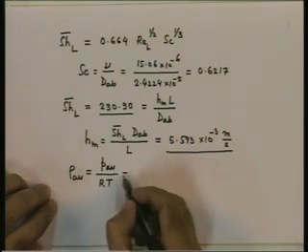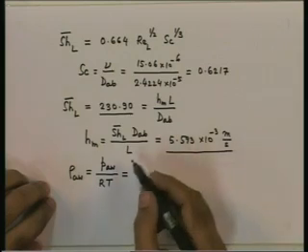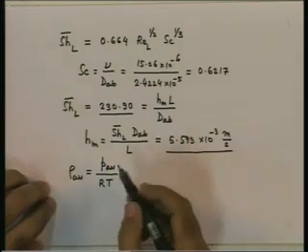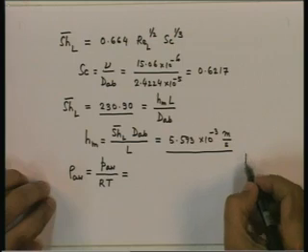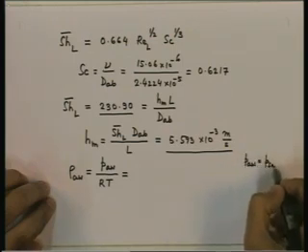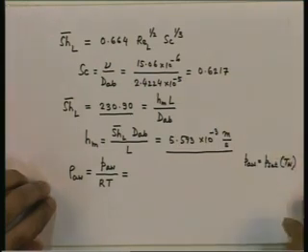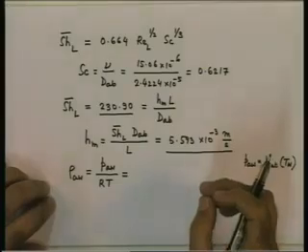The partial pressure of water vapor at the wall will be the saturation pressure at the wall temperature, because the water vapor is expected to saturate the air near its surface.